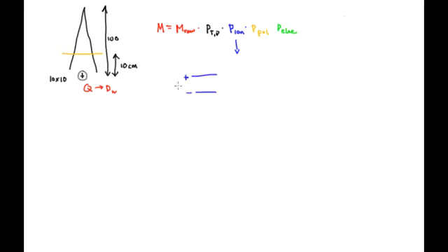One electrode is at a positive voltage, one is at a negative voltage, or at ground. So let's say it's 300 volts between these. So an electron comes in and it drifts towards the anode. Depending on where it is collected in or starts in the chamber, it could drift all the way across. As it does, it can recombine. So in other words, it combines with other atoms in the chamber, and then it's not collected because it's no longer a charge. And so that reduces the charge that's read if it recombines.